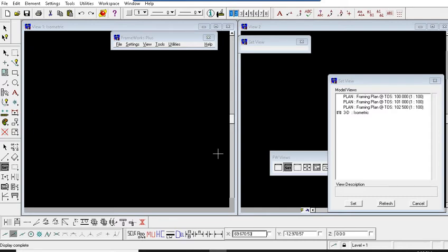When you are closing the PDS model, you should set the first view to be the isometric view by default and exit the PDS while closing. Why we set the first window as isometric is for Navisworks or SPR purposes. When they run the Navisworks review file, it will take this first window only, or if you attach a reference file, it is better that the first window is isometric. Now I am setting the 100 level to view 2.